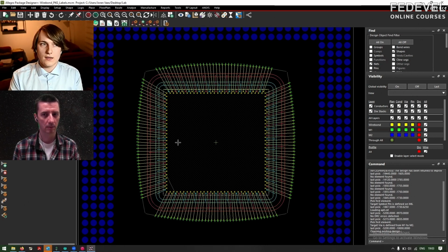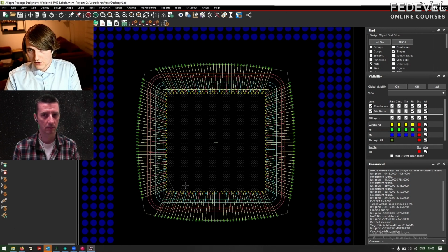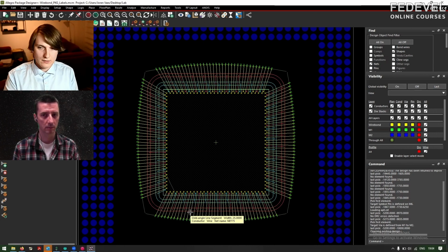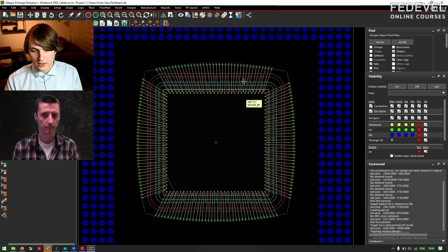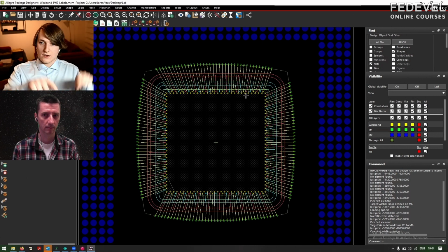The second group is a laminate-based package. This is very similar to a PCB. You have a number of metal layers with prepregs and core materials. The main difference with PCBs is that the materials are much thinner and the lines are thinner. A common package line width would be 20 micrometer traces with 20 micrometer gap, which in PCBs is already very high tech. You draw it like a PCB, make all of your connections, and it is manufactured just like a PCB. Then they place the chip on top, either with bond wires, where they put the chip with the pads upwards and then connect the wires.